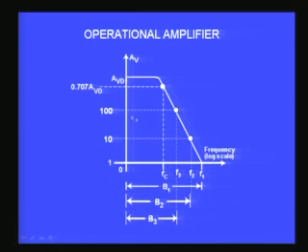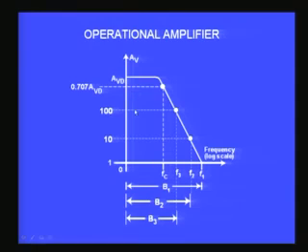If I make my gain 100, then you can immediately imagine the cutoff frequency will be around 10 power 4, that corresponds to 10 kilohertz, and that is what is shown in this graph. For 100 it comes at an earlier point in the frequency, at 10 it comes at a later point, and at 1 it almost goes to the point where the graph touches the x axis.